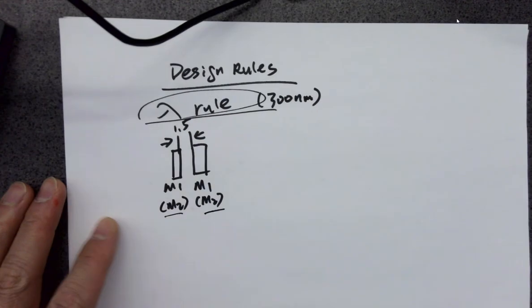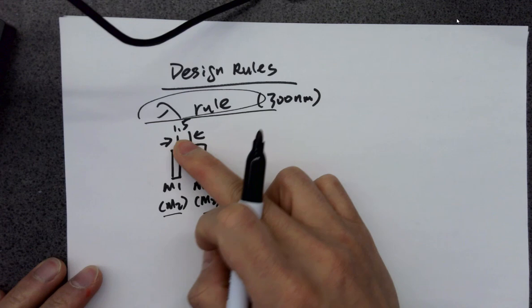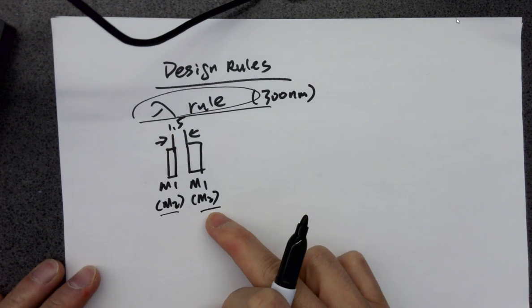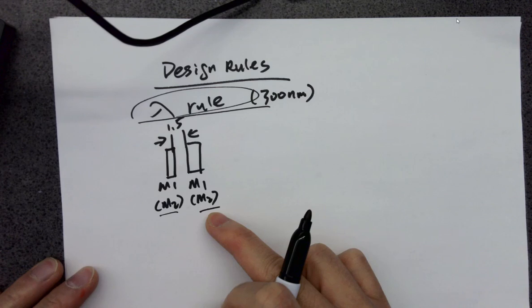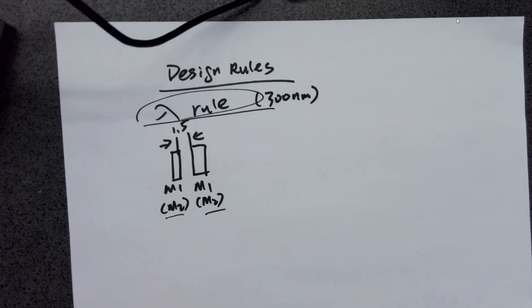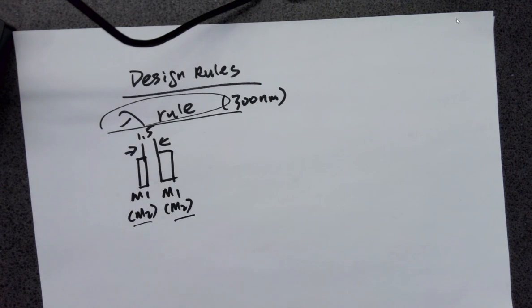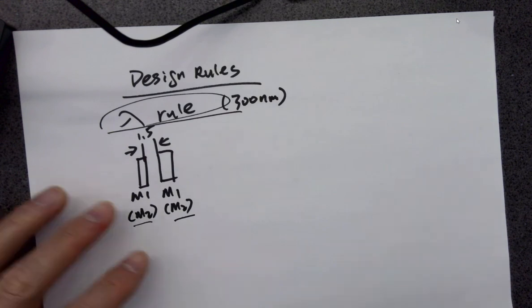The same to metal 2, okay? Metal 2. I think they have the same design rules. M1 has the 1.5, metal 2 has 1.5 as well. And we don't have to cover other rules since I couldn't memorize them either. So that's just a pass to the second topic over here, which is backup vias, which is important. You'll see this kind of layout a lot when you are just directly making a connection in layout. They'll directly generate an array of vias. You probably will be wondering why. So let's take a look at this.